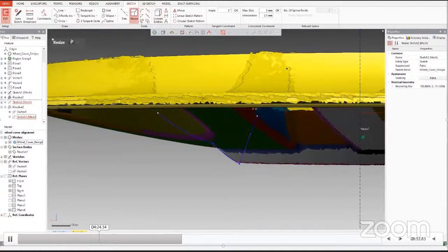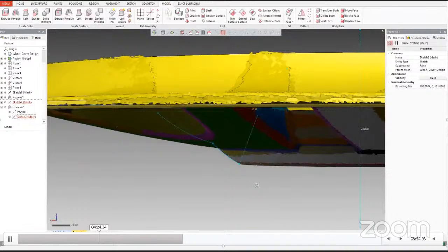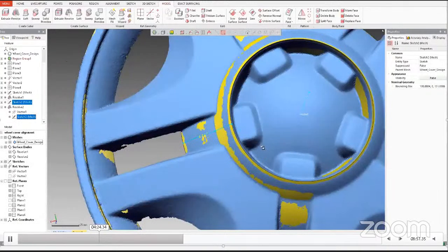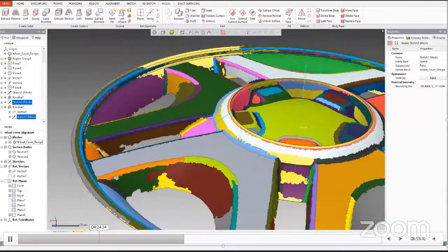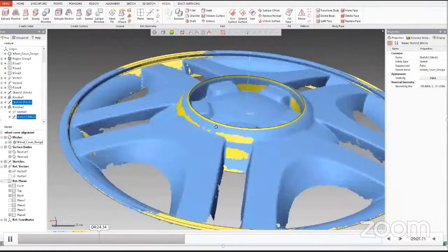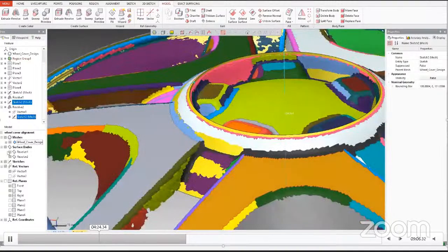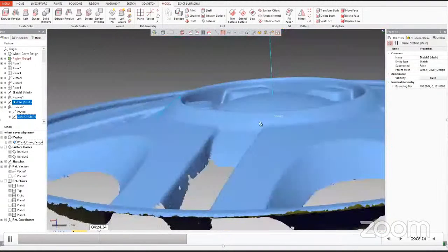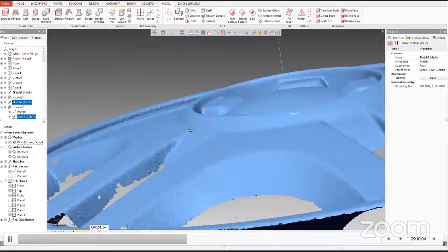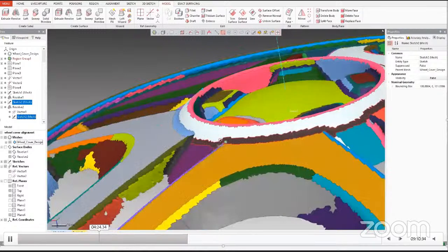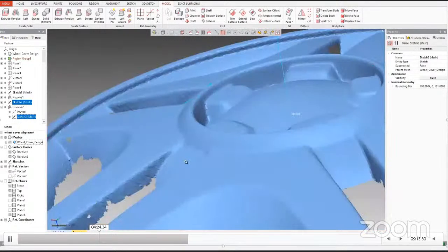So we extended the length because we want to make the sketch a little bit over the design, because in the end we have to perform the trimming operation. So this extended surface will be helpful for us to perform the trimming operation and get the more joint and connected result.